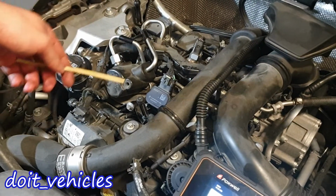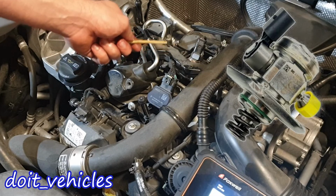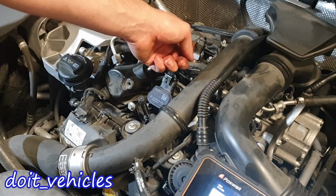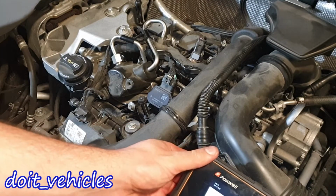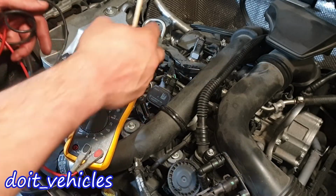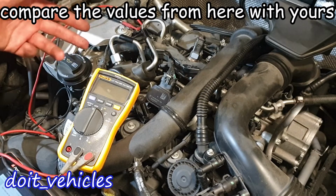disregarding the fuel pressure. The confusing part is that the same symptom is going to happen if we have low pressure or if we have too high pressure. So we need to figure that out by reading the fuel pressure. I've done that in a separate video about the fuel pressure sensor. If you want to check it out, go ahead and find it in the playlist, to adapt the diagnosing strategy depending on what you find on the live data. We're going to see the known good voltage values on the connector of the injectors, and we're going to see how many ohms of resistance you need to read on the injectors. Again, these are going to be the known good values.